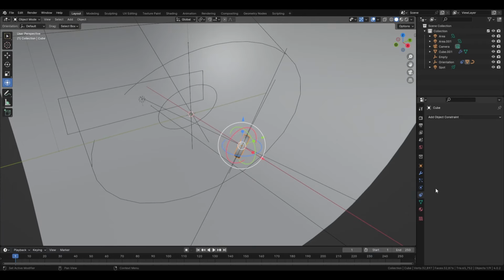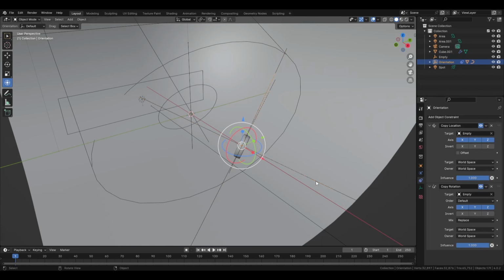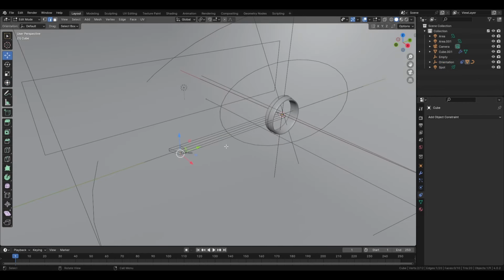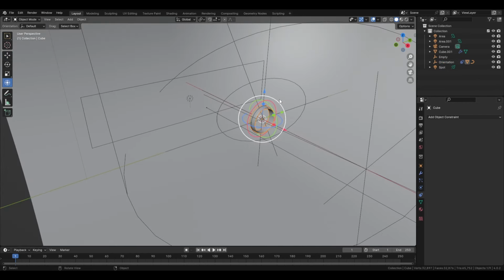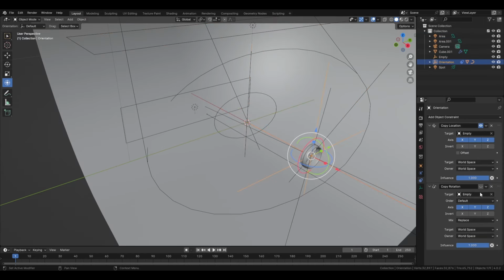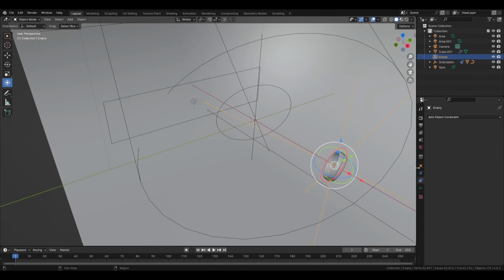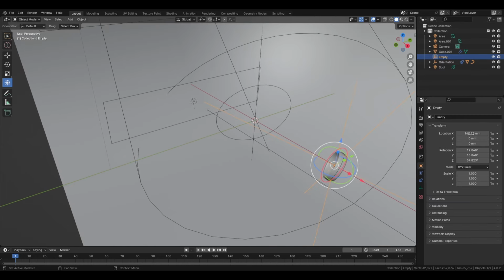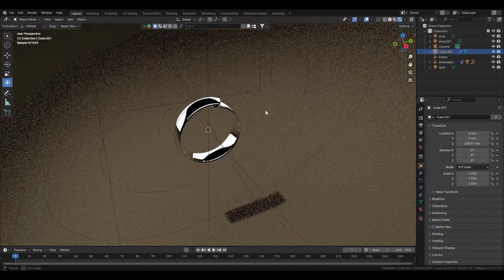without having all those weird rotation, you can. And the way you do it, what you do is go into constraint here, and you can hide this basically. So it means that you can still edit this and then come back on your empty, on your orientation, and put it back like this. Let's take this empty and put it back to its original here. So 0, and then like this.